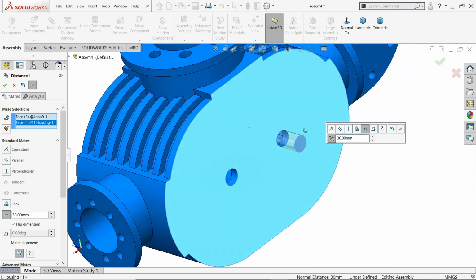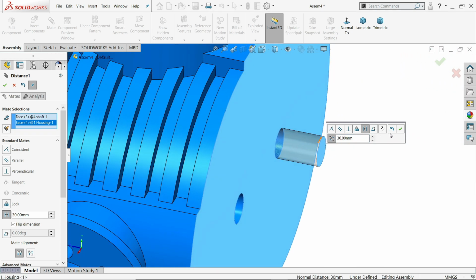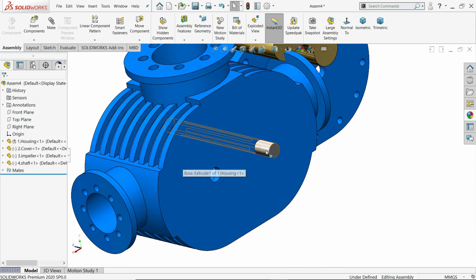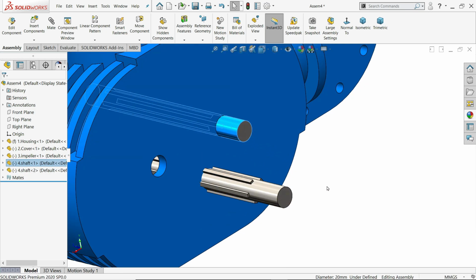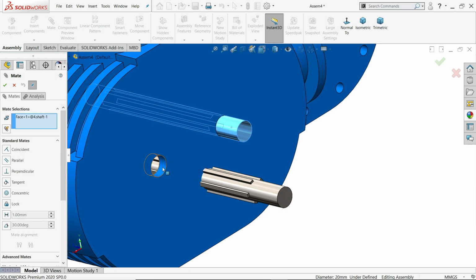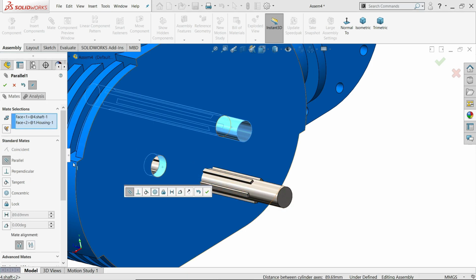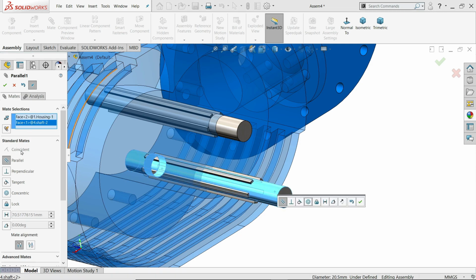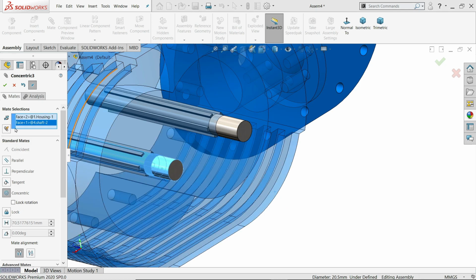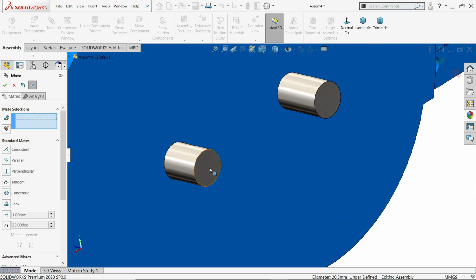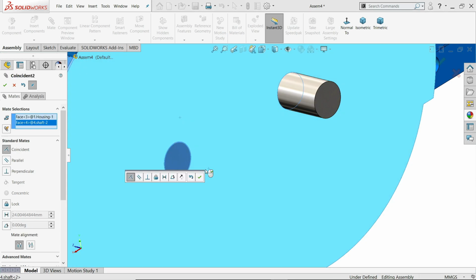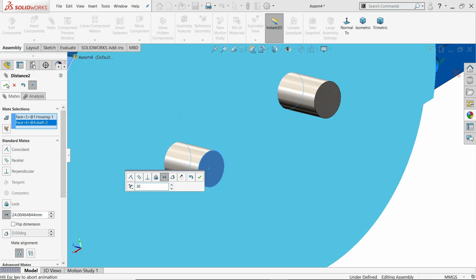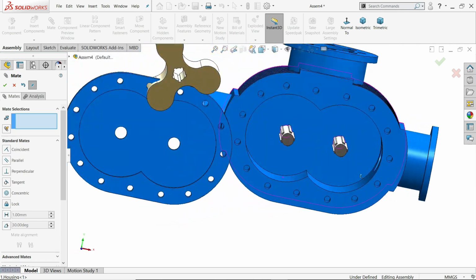Okay, that's we want to come out 30 millimeter outside in here. Now again press Ctrl key, drag and take outside. Copy, just simply a method. Clear hole and concentric relation. Okay. Here again put distance 30 millimeter. Say yes. Okay.